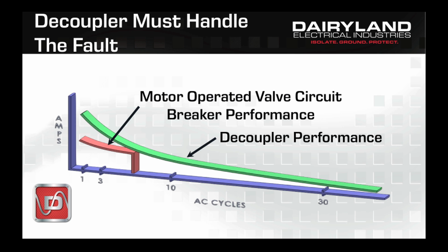So generally, we'll talk about the ratings of the circuit breaker connected to your device. If it's an overhead power line, the answer becomes a little more complicated, as not all the current will choose to flow through our decoupler, as there are alternative paths to ground. In that case, we may refer you to a consulting firm that specializes in grounding system design.